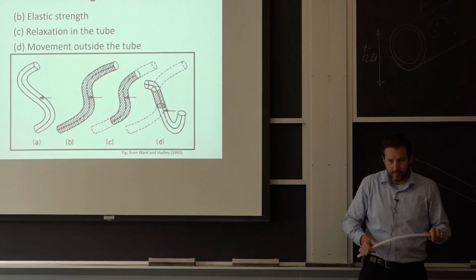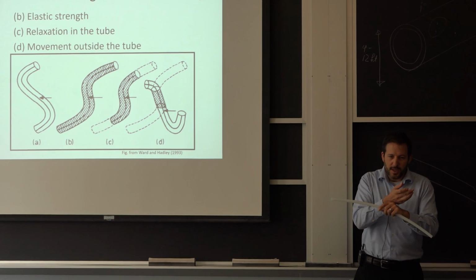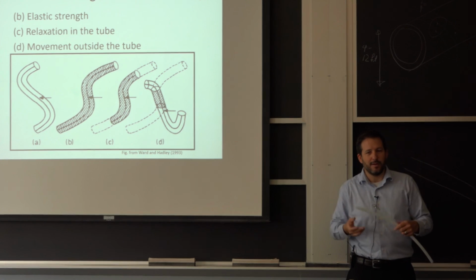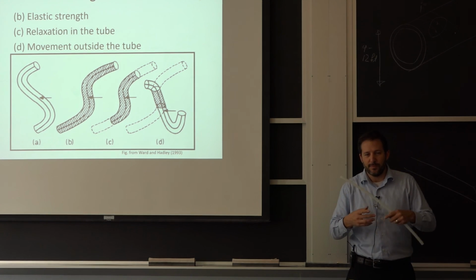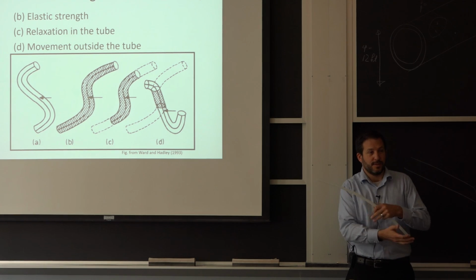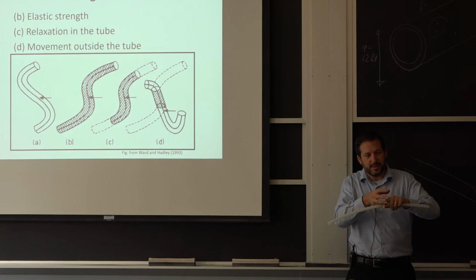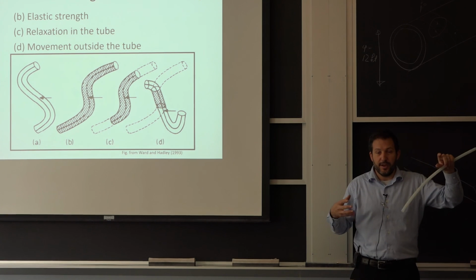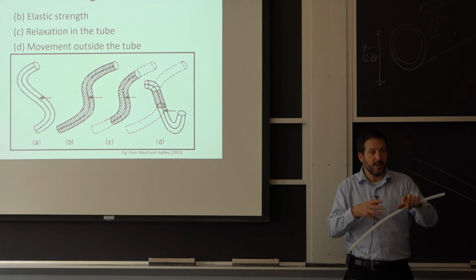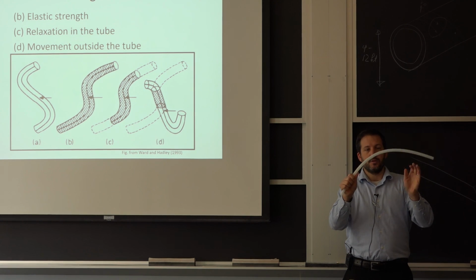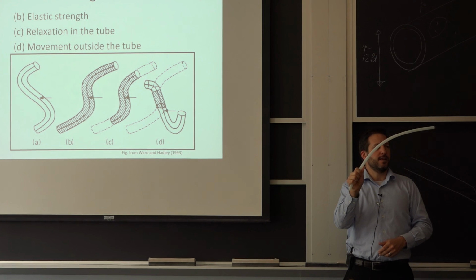It takes more time, but when that happens, then you don't really have a full history of where you were to begin with. You really are having flow that is not necessarily going to come back, because you're losing that history. When you had these little side movements that I talked about, overall, the molecules are still arranged the same way. So when you take the load off, a lot of times that goes away. So that's why if I'm doing this like this, and I let it go, there's the elastic, and then it keeps going up and up and up. That's the visco part.